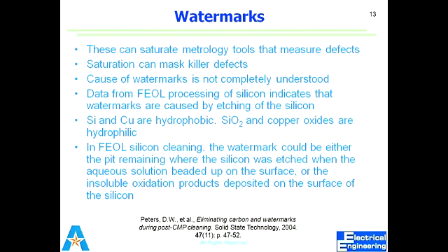has not been completely understood, what is the phenomenon behind. But some people say that there may be some pits on the surface and water actually stays in there, and some say that water actually etches away that part where it stays. But watermarks are one of the contaminations, and you always consider that there should be no watermark if you want your wafer to be considered as a clean surface.